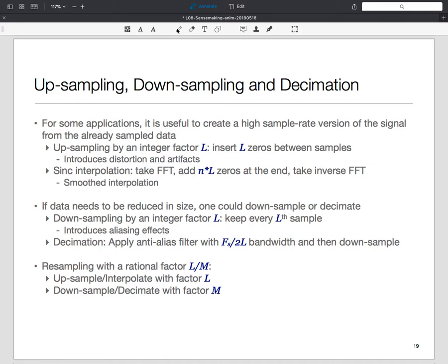The problems that come into play are, let's say I give you a signal sampled at 1 kilohertz, and I say give me the signal at 2 kilohertz. So you could say, hey, maybe I need to create a sample in between each one of these. Could I just take the average? But that's not necessarily obvious. Why should you take the average? Maybe you know something about the way the signal was changing there. So these algorithms try to be smarter about this process.